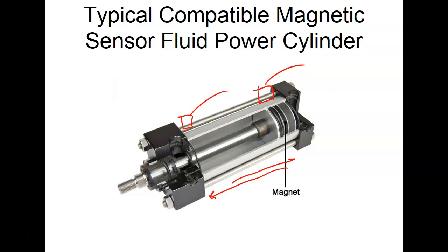because in pneumatics we don't have extremely high pressures. The highest pressure I ever saw was that Bridgestone tire, and it was about 600 psi. But they had to chill their air down, because when we compress air, it heats up for one thing, and then air can only hold so much water per cubic foot. When you compress it, the volume comes down, it can't hold the water, and it releases the water. So the problem with pneumatic systems is trying to control that water that tries to get into the